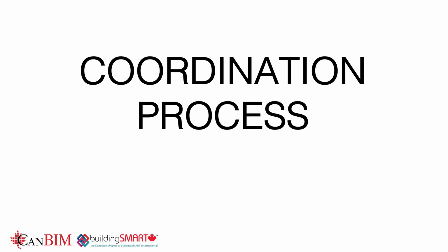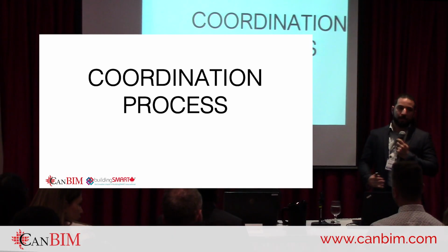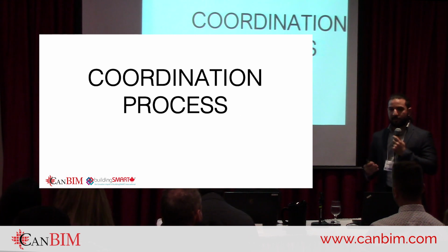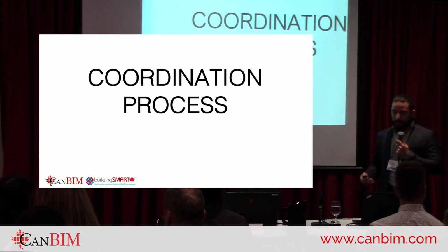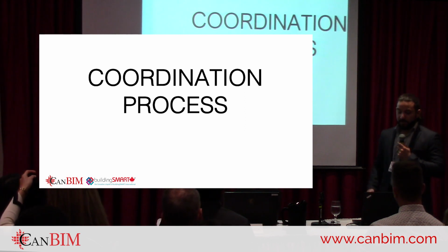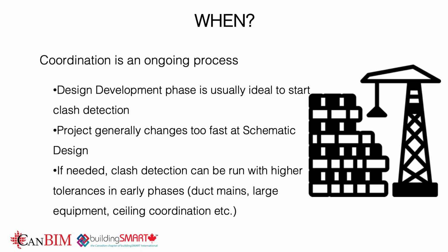Okay, so once we went through our list, and we determined which items are getting clashed and all the clash tests that we want to do, now we're getting into the coordination process. One thing I see in BIM execution plans sometimes is: we're going to issue the clash reports 2 weeks before submission, and we're going to resolve them all. No, you won't.